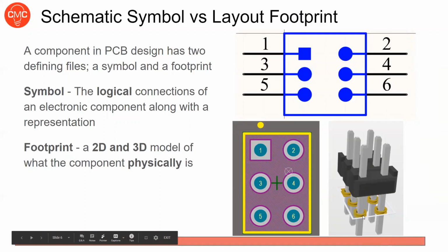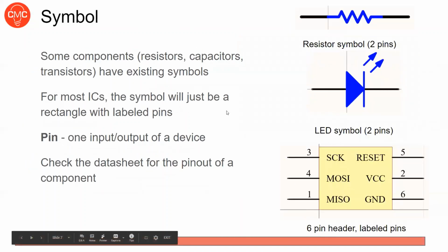This is what you're going to solder to, and you need to tell it how big you want those to be. They need to be able to fit the leads. These are the leads. You need to fit the leads through. You're going to need pads on both sides, plated so it's connected. You're going to want a certain area to show how big the part is, and not put components underneath this part because it won't fit. So you're telling it all of those things, and we'll get more into the details of this. So yeah, a symbol.